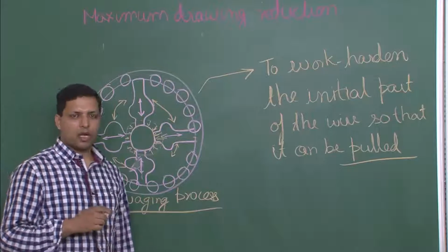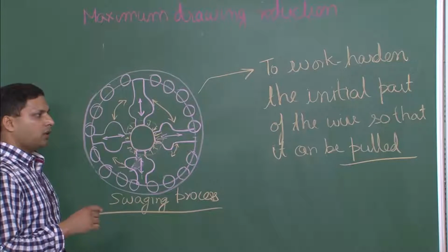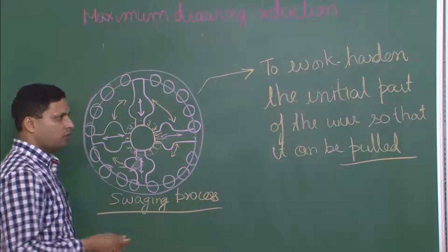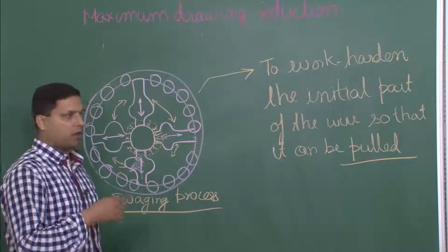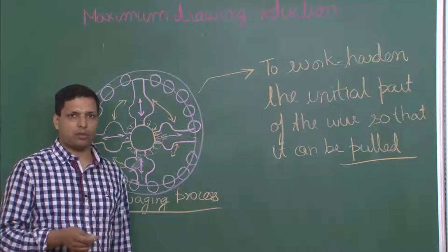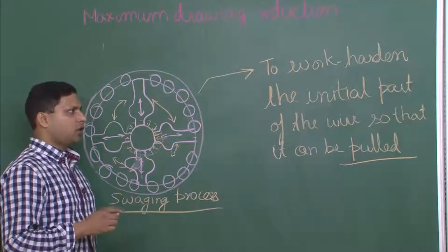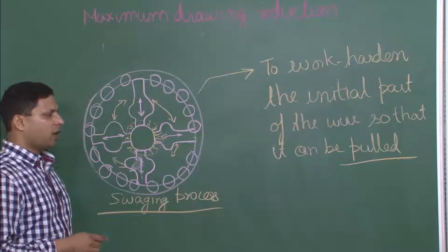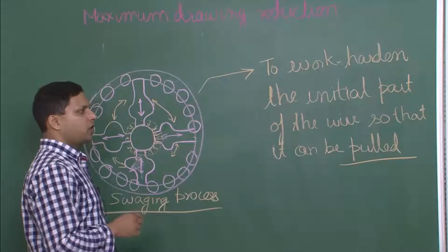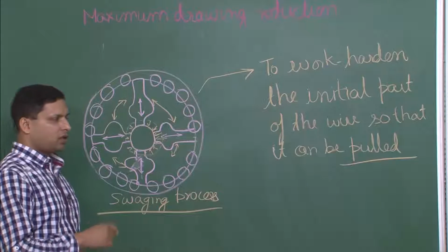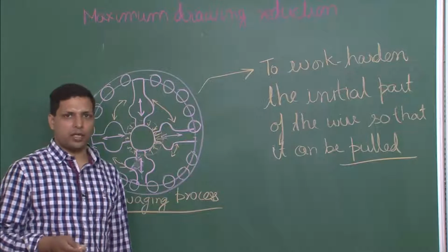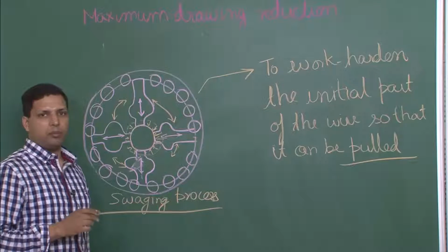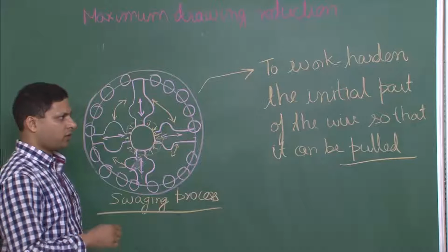We also saw that you can relate the extrusion pressure or the drawing stresses to the actual work, and if you are assuming that the actual work is equal to the ideal work, which is when no friction is present or no redundant reduction is being carried out, in that case this extrusion pressure would also be equal to the ideal work, and so we get a very nice way to calculate extrusion pressure or the drawing stresses.